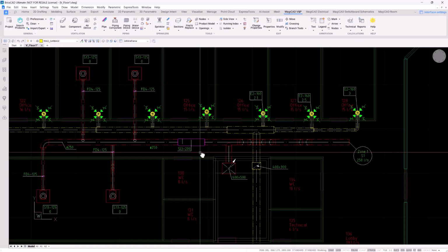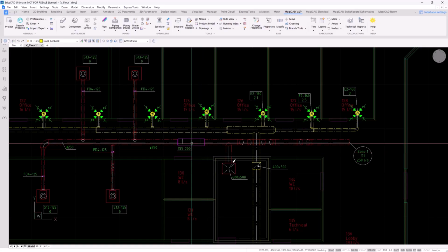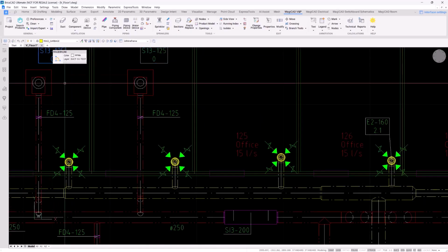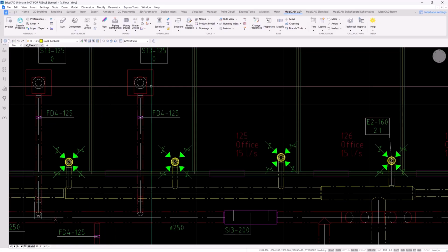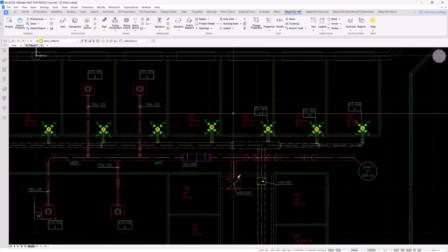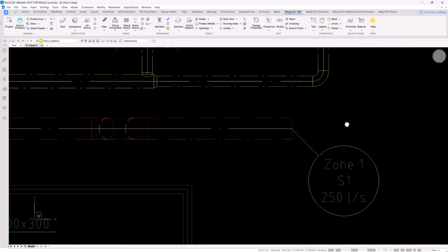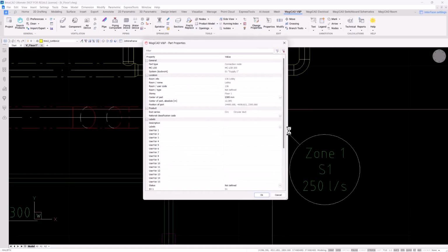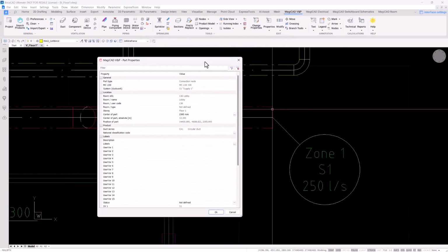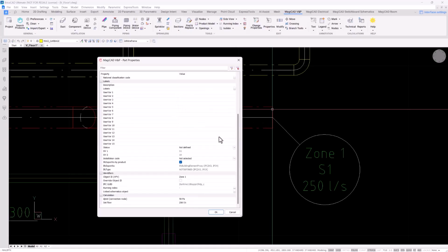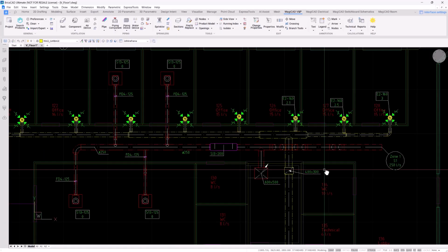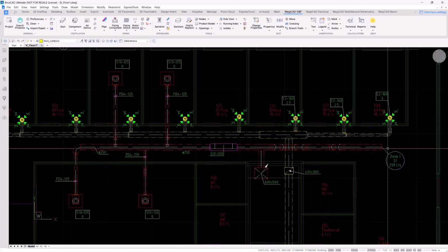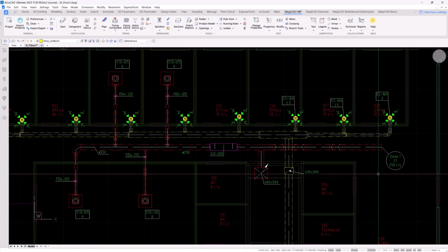So we have here the air terminals, and so far there are no damper position values here, either for flow dampers or the device dampers. And on top of the devices, I have a so-called connection node that can be used to simulate a network that is yet to be modeled. So we can define a flow and pressure level condition to simulate the consumption from this point onwards. So we can run an early phase sizing of the duct network.